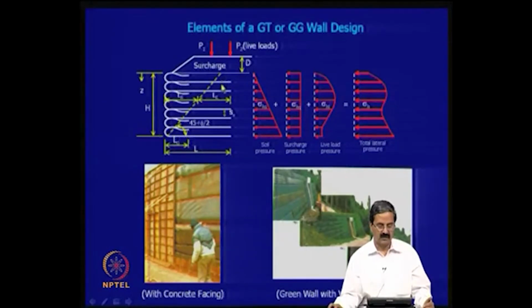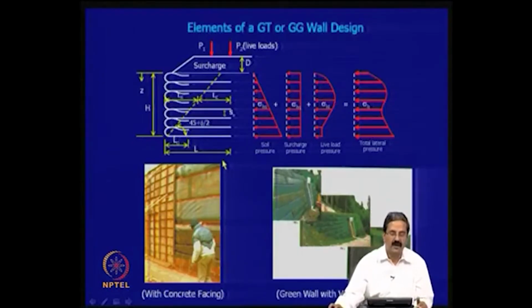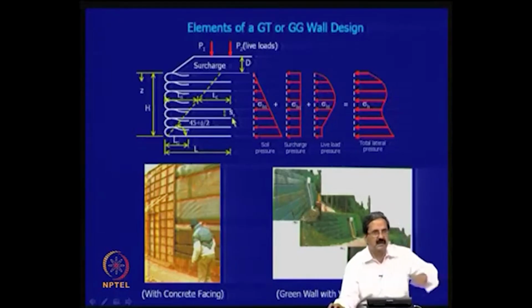Okay. So, if you are able to put at every level a reinforcement like this, then your system is fine. You can even add earthquake force also. Earthquake force adds some small changes to some of these things, and you can do that. The earth pressure distribution you can get and do that, there is no problem. There is another thing that you should know. The spacing of the geogrids, SV, is the vertical spacing, because horizontally they come in some meters, 1 meter and all. So, it is layers.